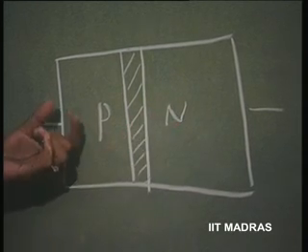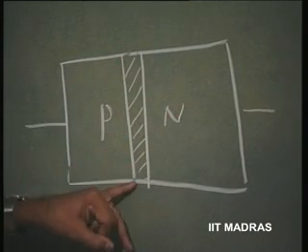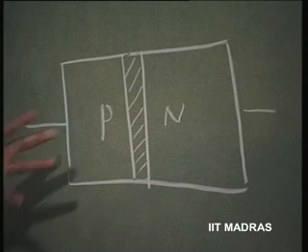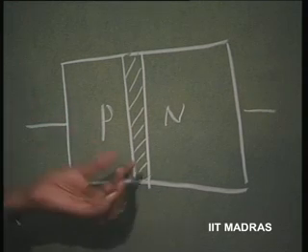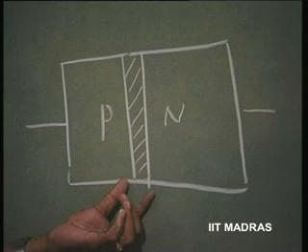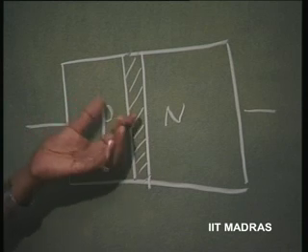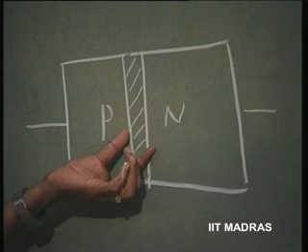Even though for the holes here as well as the electrons here there is a barrier potential hill corresponding to 0.5 to 0.7 volts, because of the existence of the depletion layer, this happens the moment I form the junction. For us to have an equilibrium here, a potential hill is created.